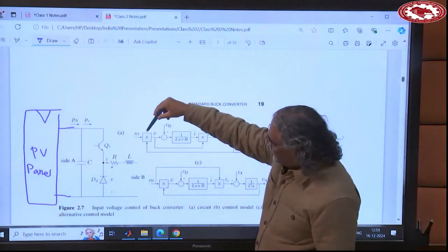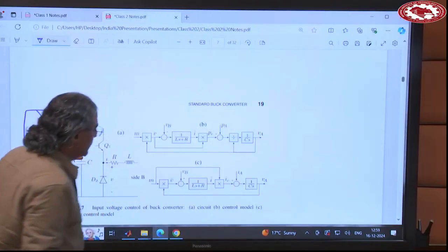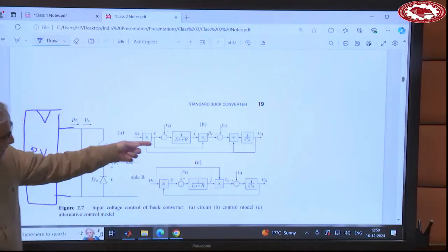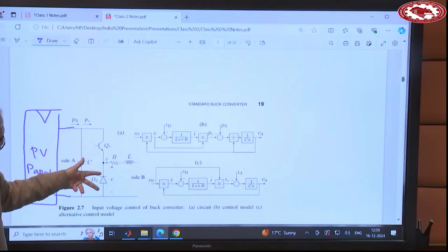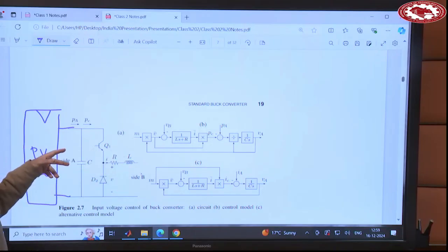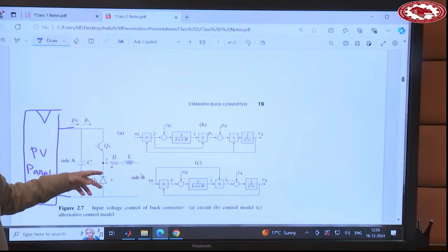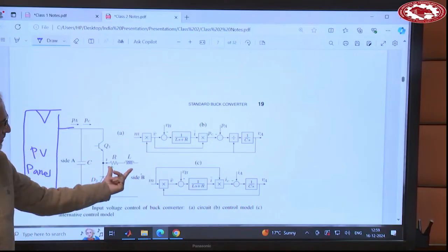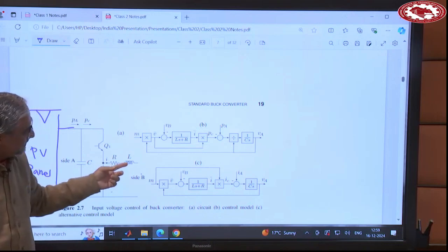M times this voltage VA that you want to control gives you the voltage across this diode. This voltage minus this voltage, which is now an external voltage. Remember, this one is now internal, which you want to control, and this is an external voltage. So this voltage minus this voltage is the voltage across the inductor, and divided by its impedance it gives its current.